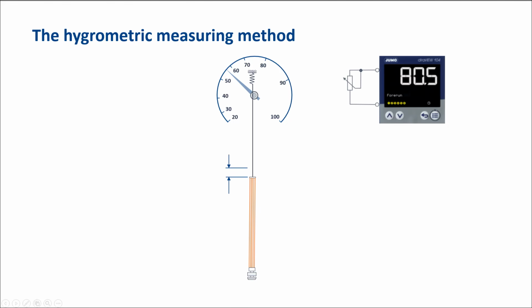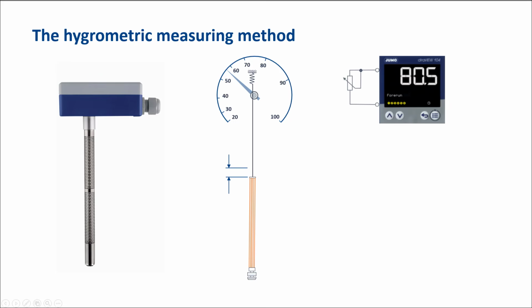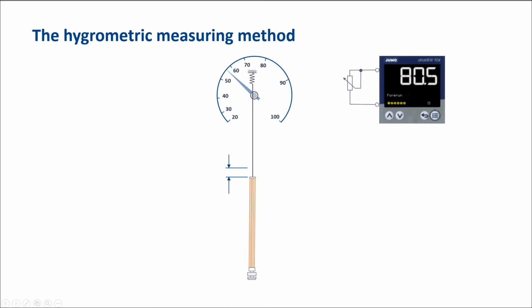The systems determine only the relative humidity and no derived parameters. The measurement technique does not require a power supply, and the principle is well suited for low-cost hygrostat construction. It cannot be used in very hot gases and is not suitable for measurement in low humidity. The so-called hygrometric humidity transducers show a relatively sluggish response and can only be used for maximum air velocities.